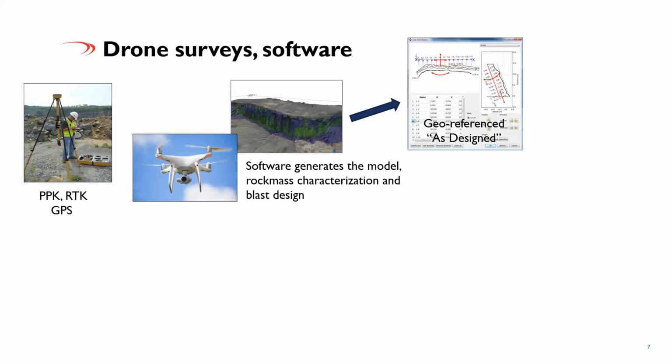The next part of this is the actual blast design. And we reference this as a georeferenced as-designed pattern. This is important because once we've generated this, this will be the basis that we'll look to implement into the field for drilling. So once this is generated, this would get passed on to the driller.